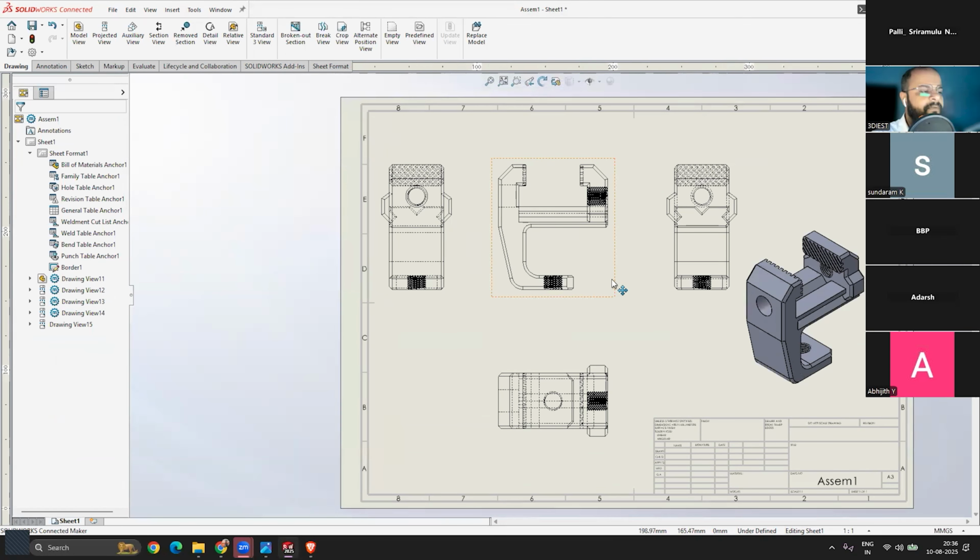For example, for this hole that you can see over here. If you add the diameter of this hole, let me add it by going to the annotation tab. I can start adding all the details. Inside the annotation tab, again, you have the dimension tool. If we click on this and drag outside, here you can see the dimension, the hole size is right now 16, right? If we click on save, it got saved. So this hole size is 16, right?